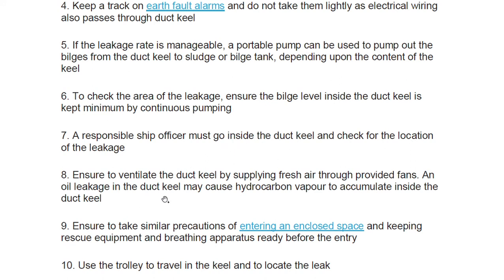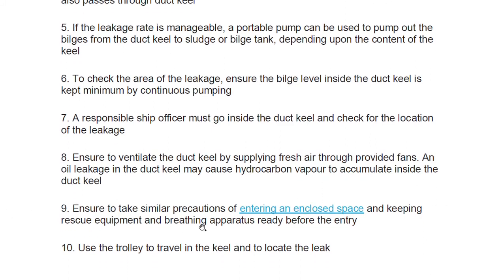Ensure to ventilate the duct keel by supplying fresh air through the provided fans. An oil leakage in the duct keel may cause hydrocarbon vapor to accumulate inside it. Ensure to take the same precautions as for entering an enclosed space, keeping rescue equipment and breathing apparatus ready before entry. Use the trolley to travel along the keel and locate the leak.